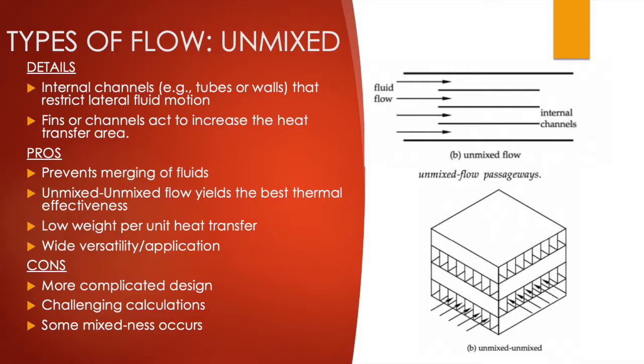Also, some cons are that they have a more complicated design versus just a regular mixed flow. There are some challenging calculations that need to be done to get accurate results, so it's very hard to pinpoint where you're going to be. And there's also some mixedness that does occur, regardless of it being called unmixed, at the tube edges and the plate edges.